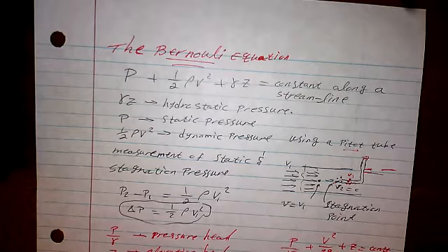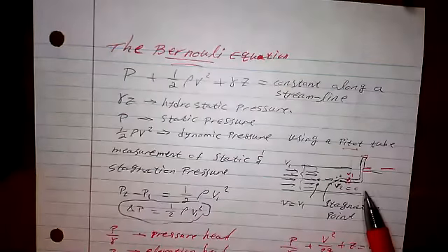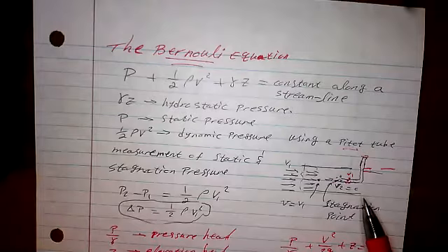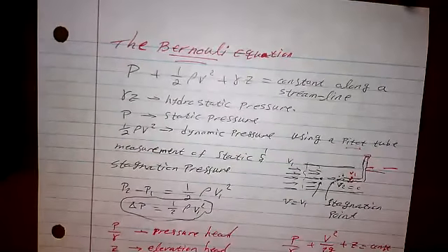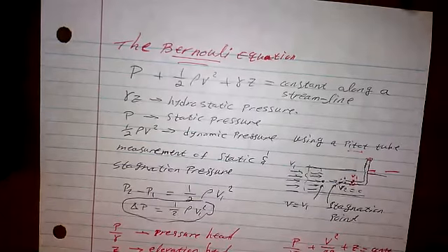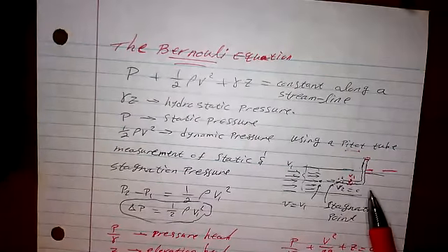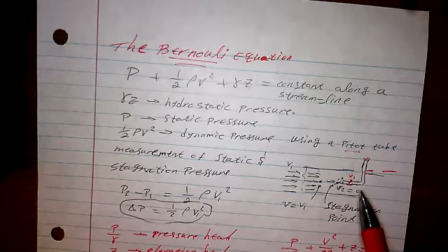The flow was going through this air duct, and then we had 2 types of measuring devices. One was a modern device we call a vane anemometer. The vane anemometer measures the velocity directly, but the pitot tube has to be connected to the U-tube inclined manometers, and that gives us the change in pressure.